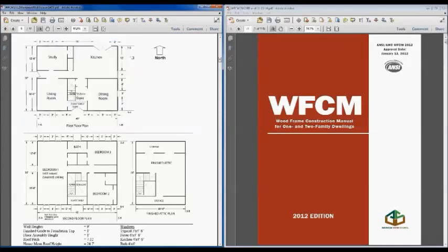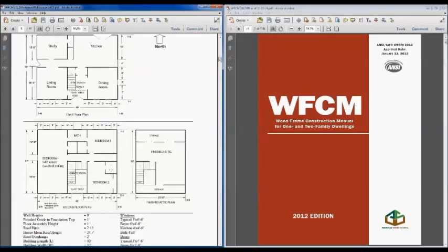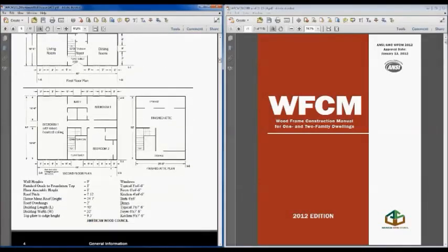The first number indicates the floor. Down here we see the second floor layout, and so we've got 2-2 and 2-1 for the walls east-west, 2A and 2B north-south, and then our attic space and the roof system. What we'll be looking at today is the third level, and so we've got wall 3A over here. If you take a look at this little note down here next to 2A, 3A is actually the little triangular gable end above 2A, which is the wall in the second story there. So that gives you an overview of some of the terminology.